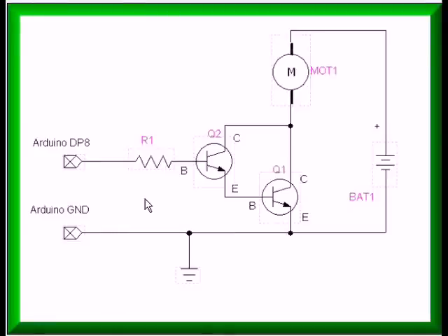Or we could connect it like this. We could take the 2N2222 as in Q2 and connect it directly to the collector of Q1. As the voltage drops here, the voltage drop will go there. It supplies plenty of current to drive Q1 doing it like this. This is your real Darlington configuration. This is how we use a low input current to get a really heavy current. And that's going to be covered in another video.